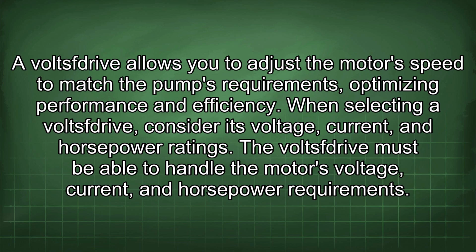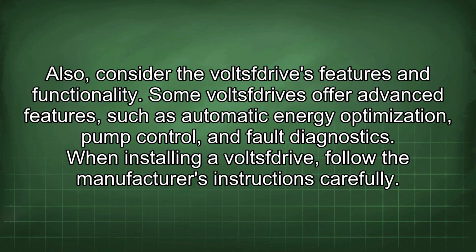When selecting a VFD, consider its voltage, current, and horsepower ratings. The VFD must be able to handle the motor's voltage, current, and horsepower requirements. Also, consider the VFD's features and functionality. Some VFDs offer advanced features such as automatic energy optimization, pump control, and fault diagnostics.